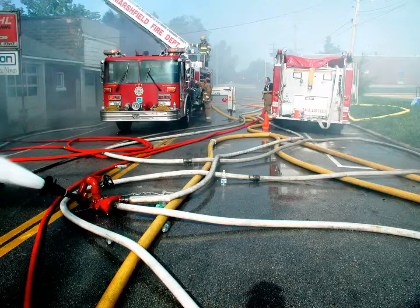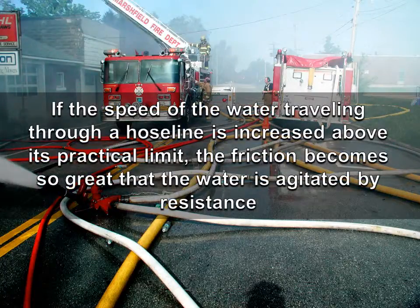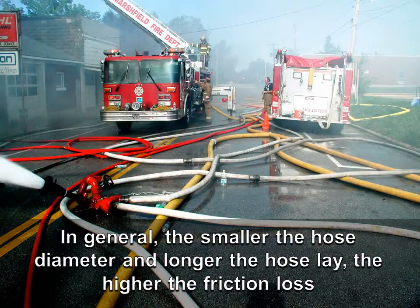The most common friction loss occurs in the hose between the pumper and the nozzle. If the speed of the water traveling through a hose line is increased above its practical limit, the friction loss becomes so great that the water is agitated by the resistance. In general, the smaller the hose diameter and the longer the hose lay, the higher the friction loss.